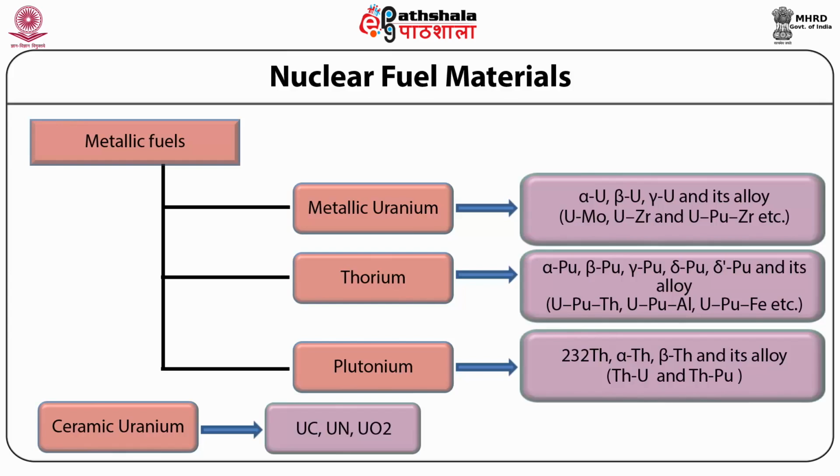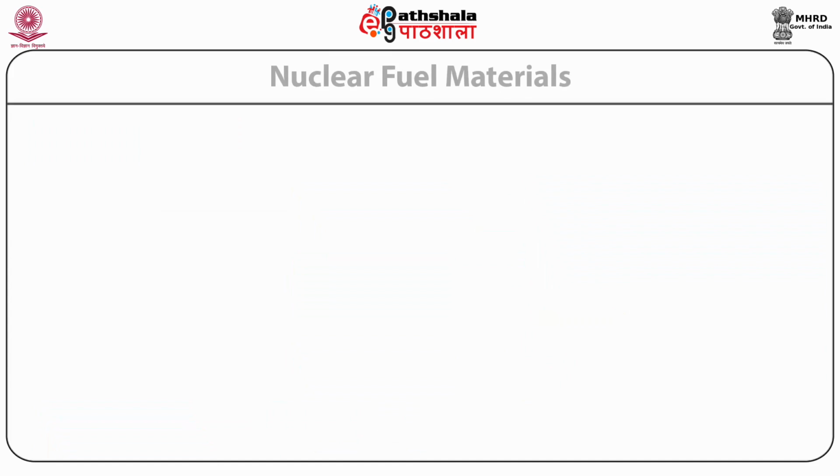After a few years, changes in fuel element design opened a gap between the nuclear fuels and cladding materials that gives a plenum volume for gathering fission gases and presented a significant improvement, 20% versus 1% burn-up over the earlier designs.